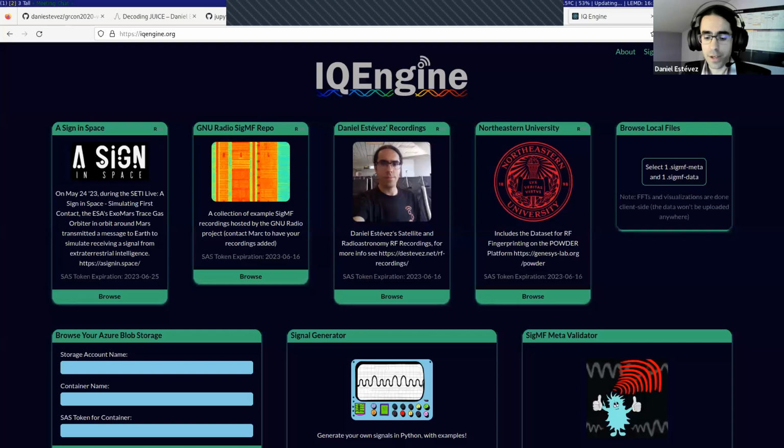And then the file is a raw file, so that means it's a sequence of 8-bit integers, and they are complex. That's a mathematical trick which is often used for signal processing. So you have the real part, imaginary part, real part, imaginary part as 8-bit integers, and you can read that with almost anything you can imagine.